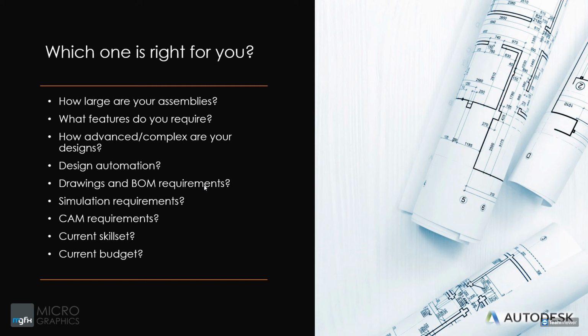Okay, which brings us to our next point. Do you require design automation, or do you have a large enough team to do all of your drawings manually if you prefer it? Also, what are your drawing and BOM requirements? You've got to remember that Fusion 360 is very limited when it comes to drawings and annotations. You don't have the full style and design library that you do with Inventor. So you also cannot do drawings from scratch.